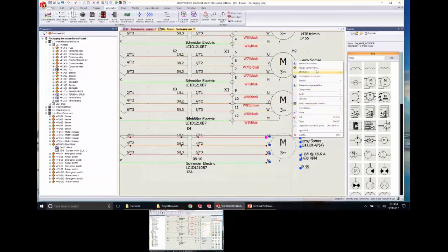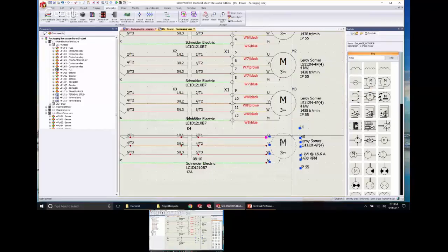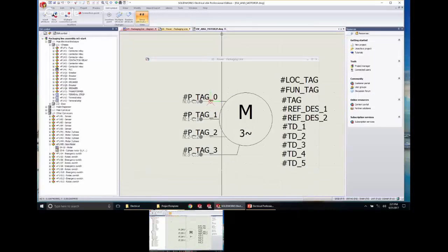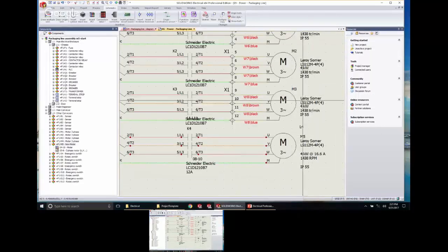So let me go here, symbol, open up that symbol. So yeah, there's all these attributes here, and you see those blank spaces in the one I brought in. It doesn't have those, so they just show up as blank. If I created this, I move these attributes around so they're next to each other. That's it. Good question. Yeah, always a good idea.